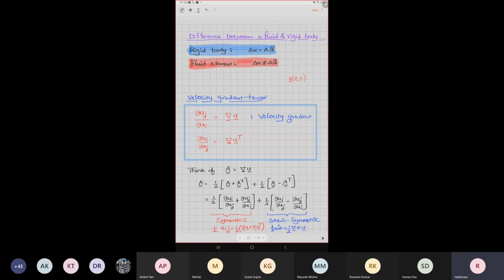Based on the measurement, where we are going to keep our probe or how we are going to visualize things and so on, we can always construct gradients of velocity. Though velocity is a vectorial field, the gradient applied on that is going to give me a second rank tensor. And this is a very fundamental quantity to understand any complex fluid mechanics problem.